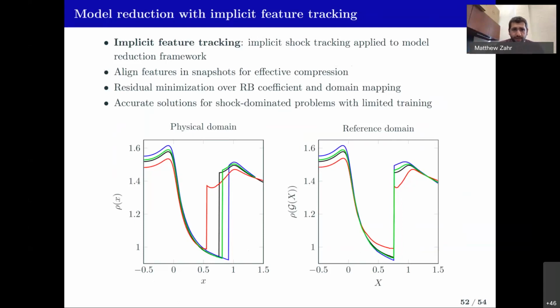And the reason that I brought this up is because element collapses are, I don't want to say trivial, but they're easy, they're straightforward. You can do them for any polynomial degree, you can do them for any dimension. In our code, we have a dimension independent simplex collapse where it would work in 8D because of the known structure of simplex elements. It's different with hypercubes or cuboids in general, because if you collapse an edge, you're not guaranteed that the volume goes to 0. So you have to decide what to do at that point. Do you continue to collapse edges until the volume does go to 0? Do you try to work with degenerate elements? It's just not obvious exactly how you would want to handle that.